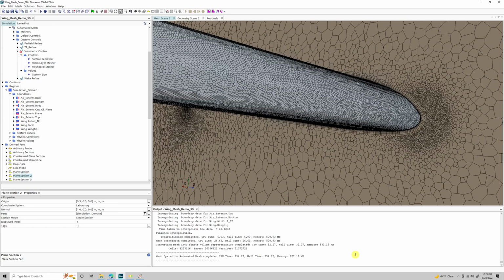So, we started a little bit with, I believe, the derived parts. We can see what a polyhedral mesh looks like. We talked about setting up some probes so you can measure things: point probes, line probes, arbitrary probes, presentation planes, section or presentation grids for measuring points on a grid. Plane sections, we also have cylindrical sections, constrained plane sections, spherical sections. You could cut up your domain in a bazillion different ways. Streamlines, those will come back. Believe me, they'll come back.